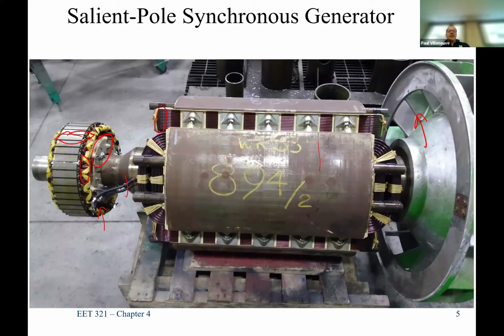What's the ratio? And the answer is it depends on the speed of operation, right? The number of poles you're going to have here, this one might be a little easier to figure out because you have these big windings. But over here, all I need to do is get DC out. So why do I care what the frequency is? It could be 10 million hertz, right? It's immediately going to get converted to DC. So this one, it looks like there are lots and lots of windings that go through there. But the reality is, it's whatever it needs to be for the diodes to be happy. So I don't know. And you can't tell because if you look closely, let me erase a little bit. You've got to really look closely, but some of these windings, it looks like this one goes over here. So that's the same phase current. That could be another pole pair, or it could just be distributing the winding on the perimeter of that shaft. So you can't tell by looking at that.